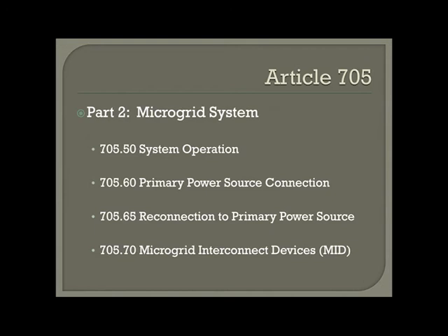marking. Is everything labeled properly? Besides the fact that it's maybe wired correctly, maybe it isn't. There's no stickers on it. First of all, one of the biggest things is you need to tell LES where's the disconnect at. So the meter's right here, the disconnect's here. I don't care, you still label it. The meter's 2 foot to the north, okay?